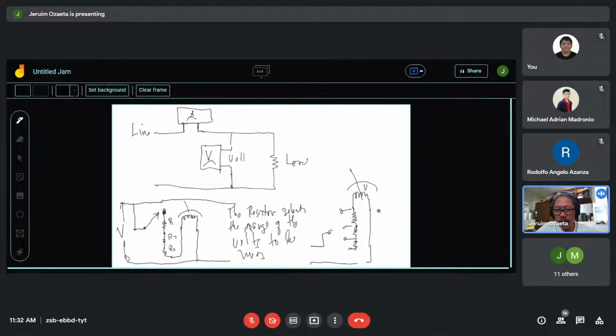So that the current in the coil, I sub coil, will be from the source E and the resistance R sub 1, R sub 2, R sub 3. So I at the coil will be equal to E over R sub X, whatever resistance is selected.